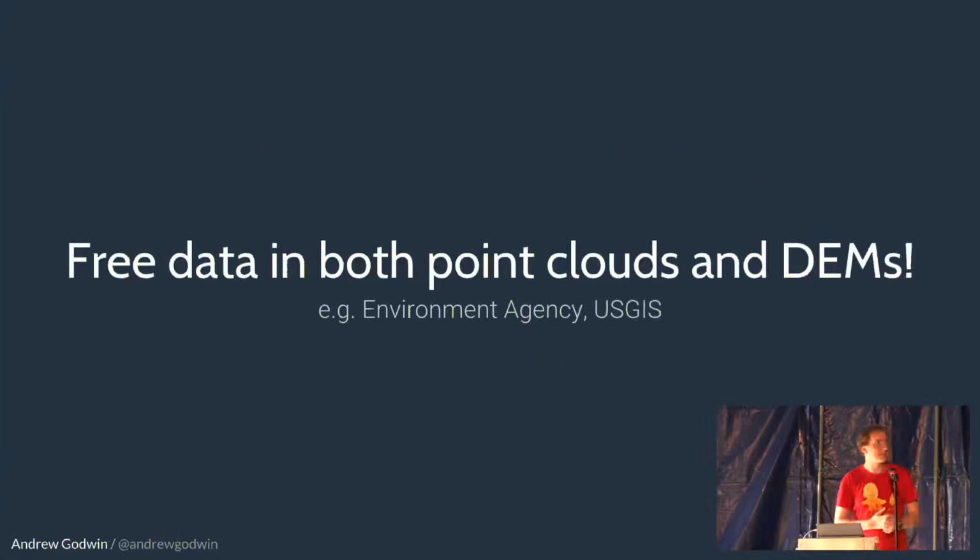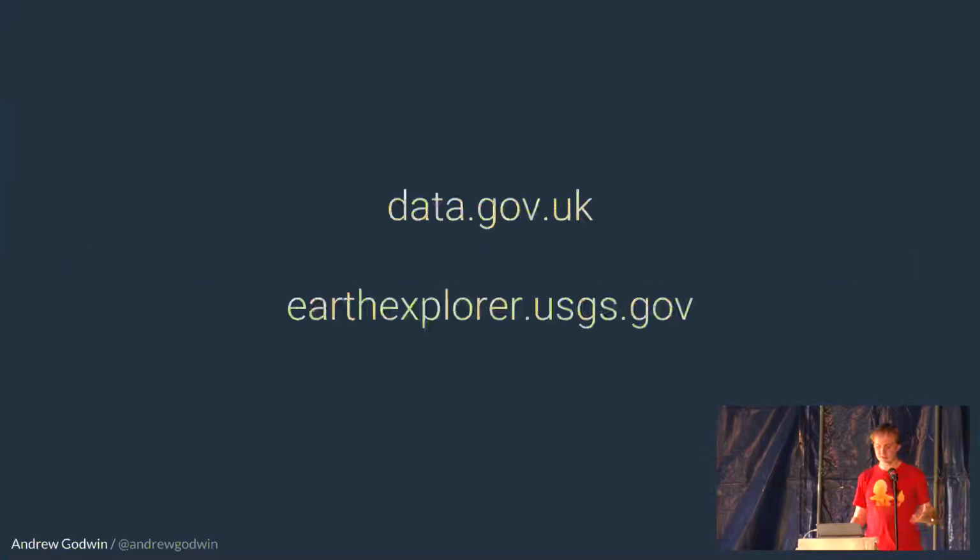And one of the nice things about LiDAR in general is that even though it's very expensive to do, a lot of free data is available from different governmental departments. In particular, our very own Environment Agency and other parts of the UK government have free data available. The Environment Agency have basically mapped most of the floodplains and coastal areas in the UK with free LiDAR, and I believe there's an ongoing project to map a lot of the rest of the country in LiDAR for free as well. And over in the US, the Geological Survey have mapped most of America in a sort of low resolution, and again, a lot of floodplains and coastal areas in high resolution. LiDAR is often used for floodplain modeling and analysis. That's where you see it often, more near cities and rivers and things.